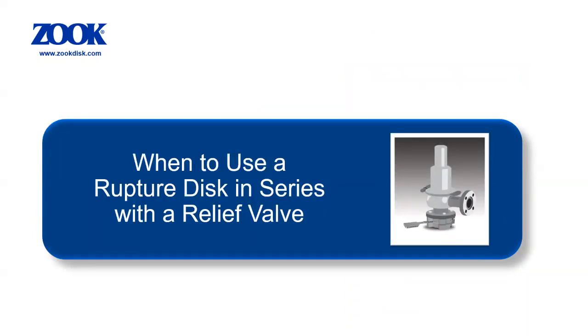Ben mentioned earlier an application that includes a rupture disk device in combination or in series with a pressure relief valve. For this application, the sizing is based on the pressure relief valve capacity. The effect of the upstream rupture disk device is accounted for by applying a default 0.9 combination capacity factor, or CCF, to the valve flow capacity to give a conservative relieving capacity for the combination.